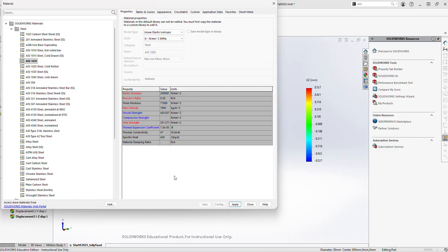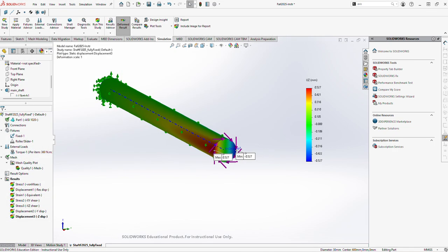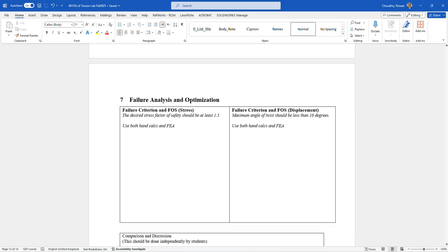So what I would recommend is that, based on what we covered in the lecture section about the different types of failure criteria, like the Tresca criteria, and also considering the type of the material, you first get a value of the shear strength for your material, and then use that to calculate the factor of safety using the shear stress criteria.